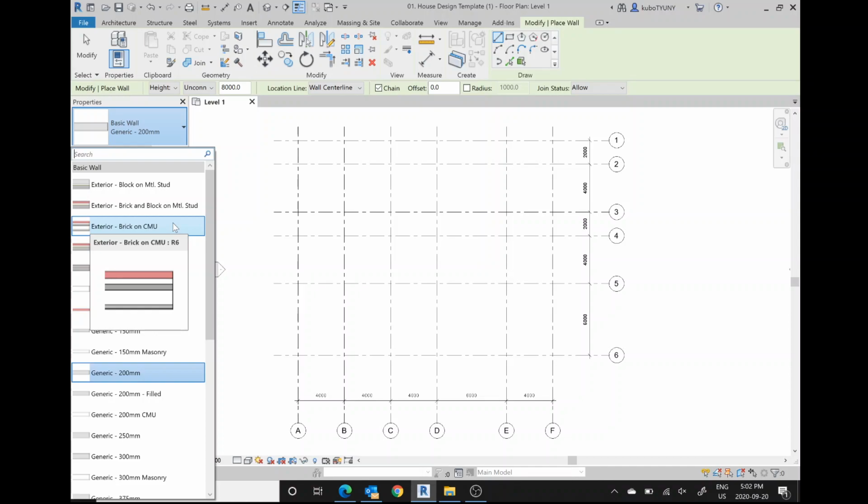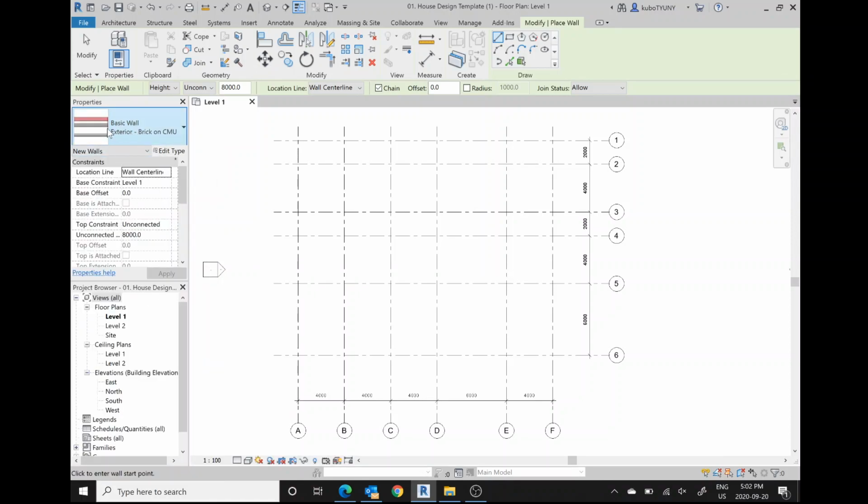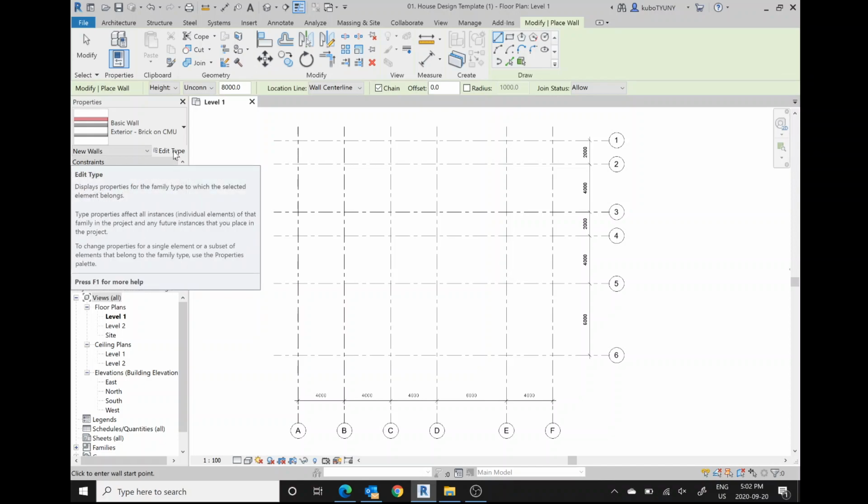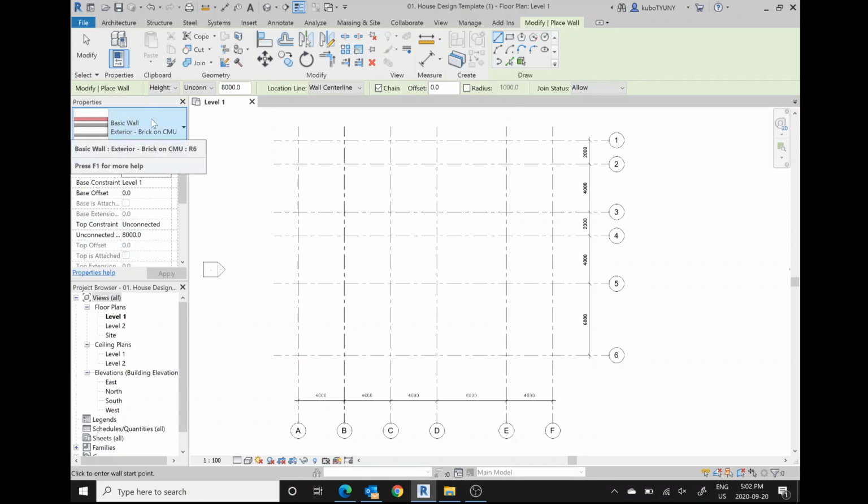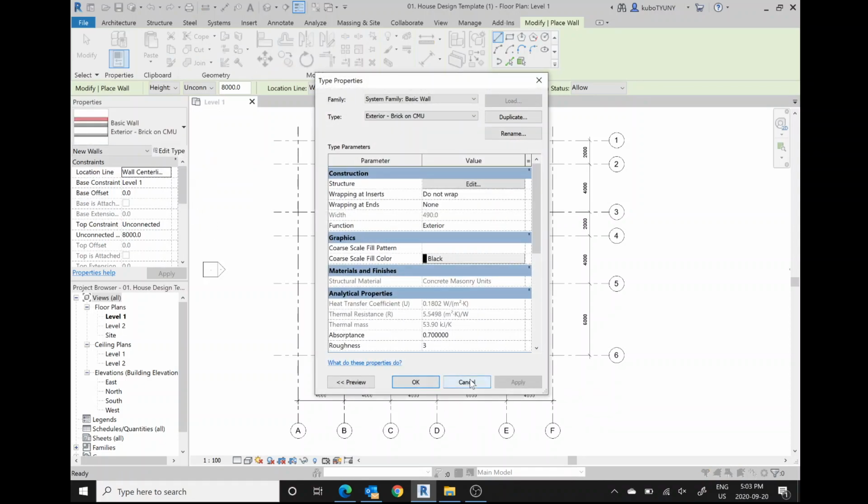This is not typical for house construction because concrete masonry units are concrete blocks, so about 200 millimeters wide, or 8-inch concrete block. And then it looks like it's got a couple of layers of other things on there and a brick veneer. So maybe you would have this in a commercial building, or as a residential foundation wall that sticks above the ground, because often foundation walls are built out of concrete block or poured concrete. But if it sticks above the ground, let's say half a meter, you still want it to have a nice brick veneer just like the rest of the house. So this might be the type of wall you see used for a basement on a house or some kind of commercial construction. Oops, I'm just going to go back a sec.